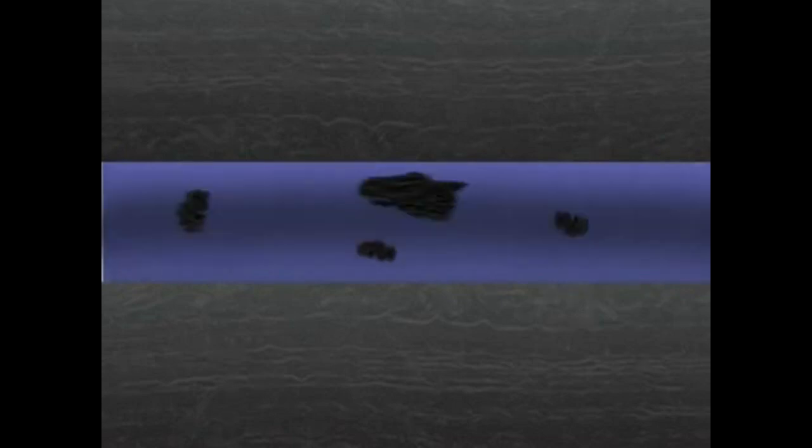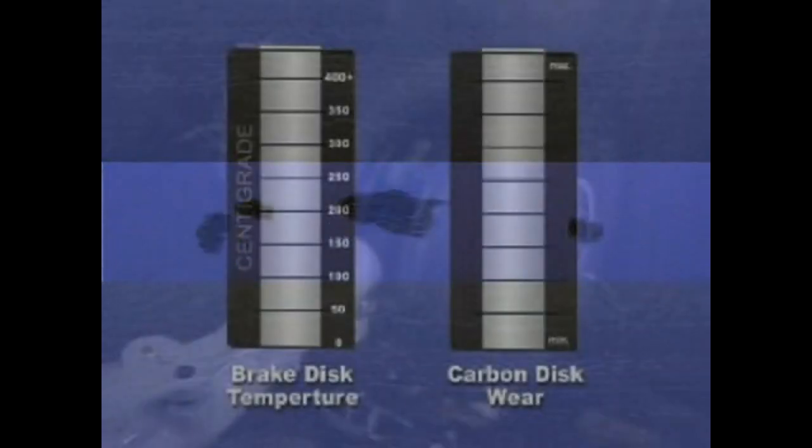As these large particles grind down, they continue to remove material, but begin to generate film-like debris. This debris acts like fine sandpaper and inhibits the formation of the large abrasive particles, thus reducing wear. Large abrasive particles can form at any time, but are most destructive when the brake is at a cooler temperature. When the brake is cool, the process of wearing down the larger particles is slow, and the particles cause more wear before they erode into a fine film.